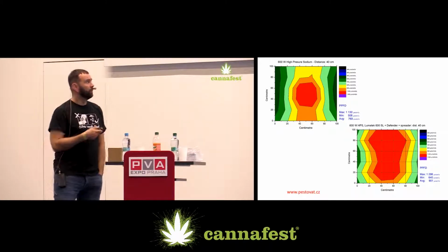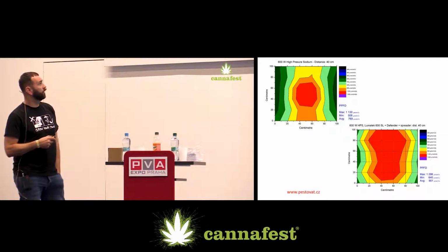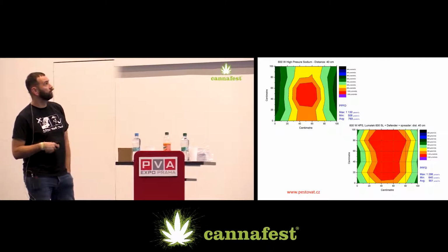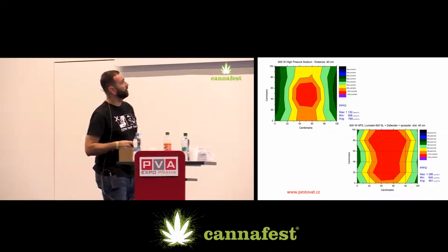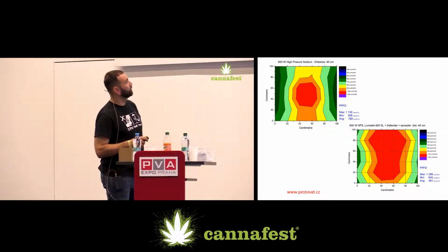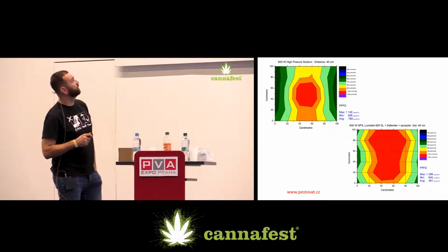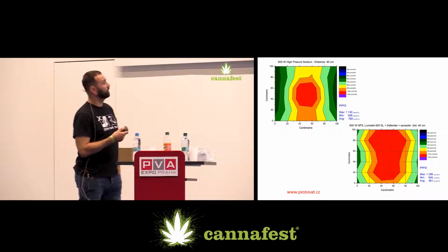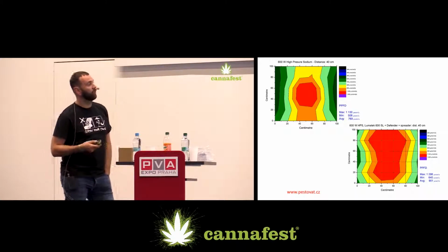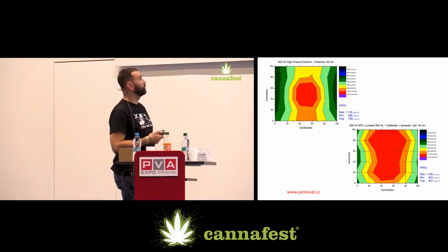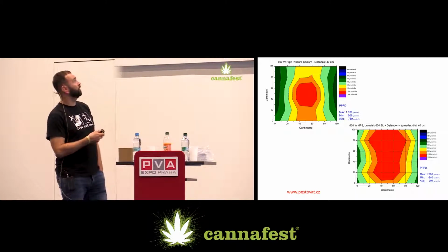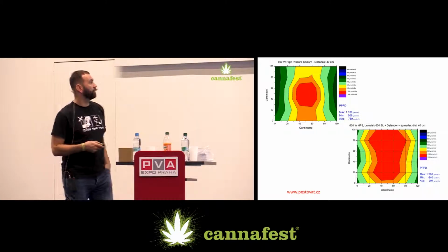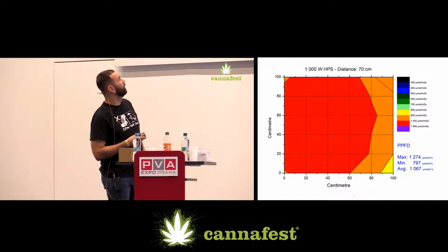As a matter of interest, I also show you a comparison of an ordinary electromagnetic ballast resistor with a fully electronic ballast resistor. 40 centimeters, the same distance, but a different ballast. It's an electronic one, and this is the electromagnetic one. You can see that the difference is again about 15%, as I've mentioned before. So I'm getting a savings, but then I'm getting a loss.